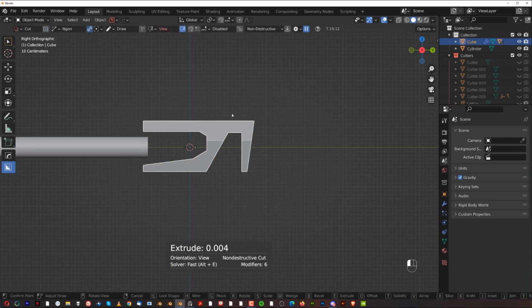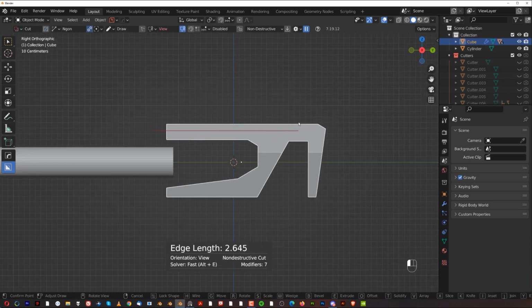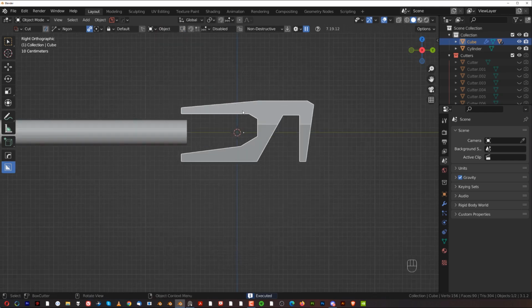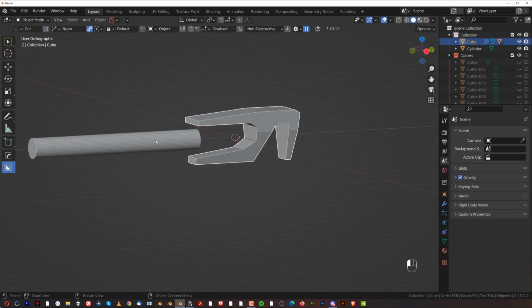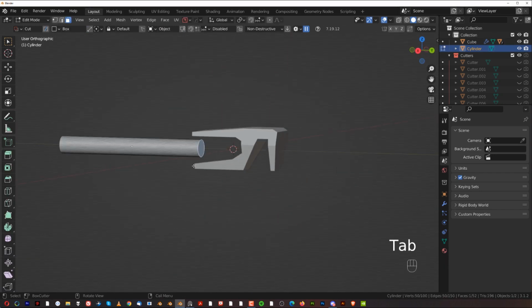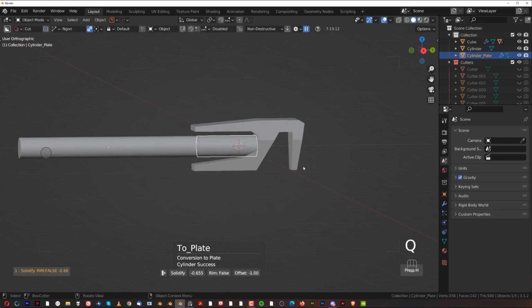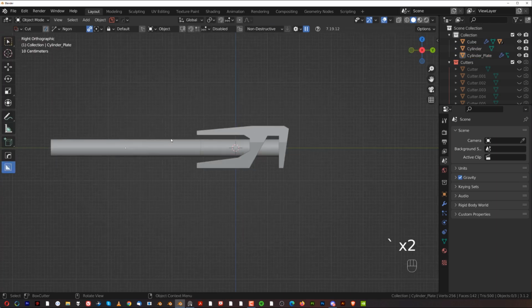Boom, right? And maybe slice it here from the top, and then we could slice it here to create some interesting shape on the top as well. Boom. So you're gonna have these two lines here corresponding, sort of echoing one another. This one should be deeper, but we can create a second part. So Shift curve extract and edit in here. We could extend it all the way up here, and we're gonna have two parts.